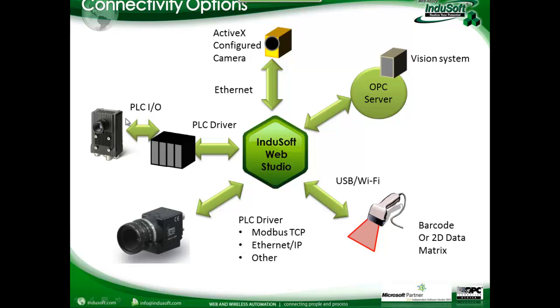Another way might be that the vision system itself might not have a PLC protocol, but it might act as a sensor where it's a switch, an on or an off. In that case, it might tie directly into a PLC input, and then we might use a PLC driver to communicate to the PLC and get the information from the PLC as opposed to directly from the sensor itself.